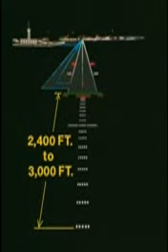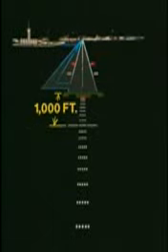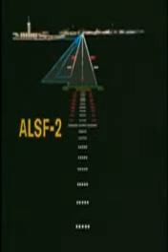One of the first things you will probably see with this system is the sequenced flashing lights. They extend to the distance marker 1,000 feet from the approach end of the runway. The ALSF2 system includes a row of red lights on each side of the center line and another row of white lights at 500 feet from the runway threshold. This system provides additional runway guidance during the more sophisticated instrument approaches.